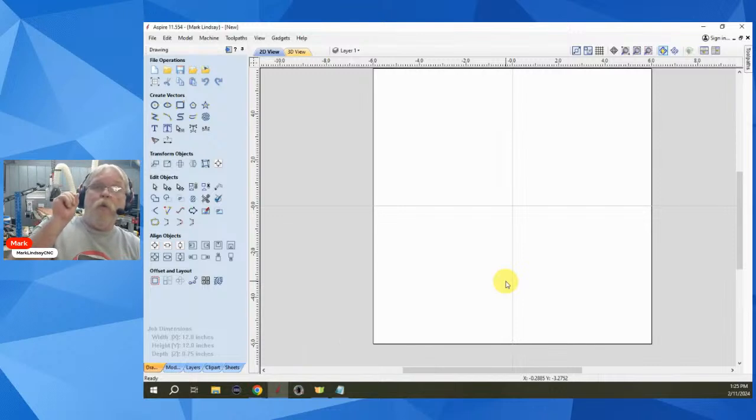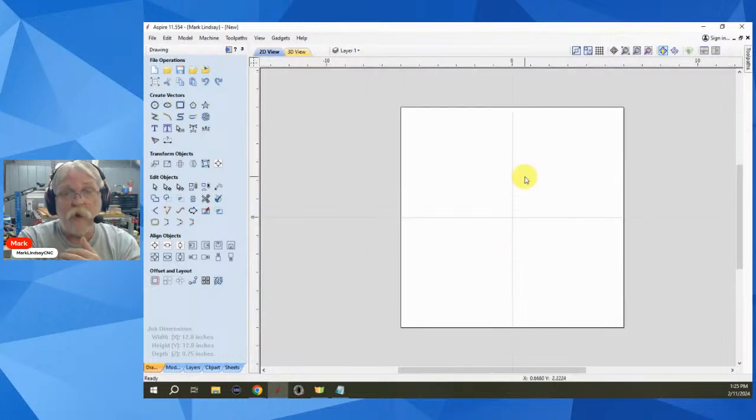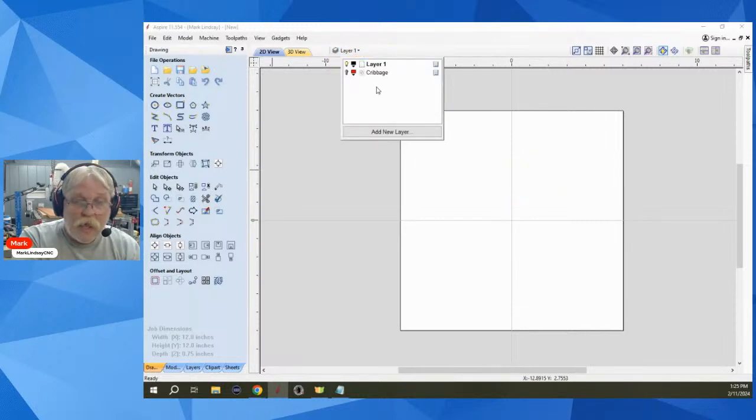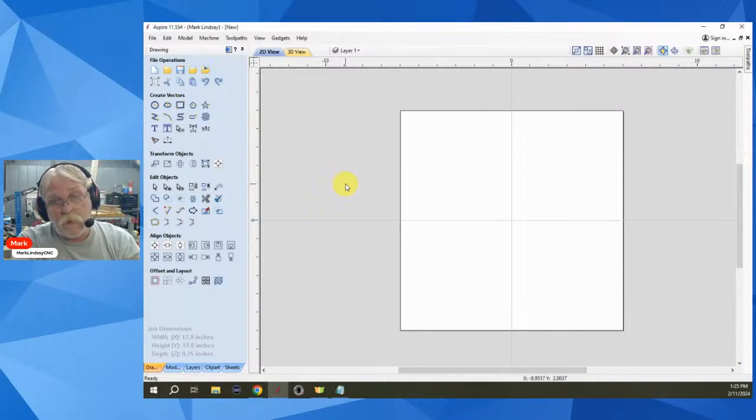Again, once a vector is imported, it's just a vector. But you specifically mentioned PDF files. Let me remind you something about PDF files. No, not all PDFs are created equal. Check your layers. You may have more than one layer visible, and the two pieces that you're trying to connect may be on different layers. So not all PDFs are created equal.